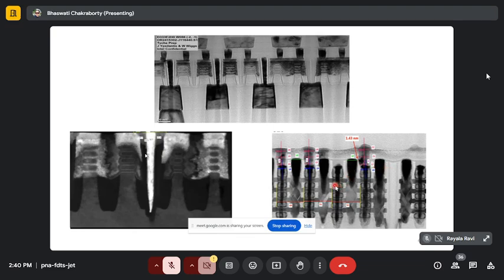Yeah. So these are basically the ribbons, the gate portion, and my job previously was working on something which was in here. That is the contact segment, which was called Interconnect 2, and this particular thing is called deep via. This deep via connects several interconnect layers which are stacked on top of each other, and connects several links with this via structure. I was associated with one of the contact segments, which was called Interconnect 2. So there are several links over here in the contact portion.